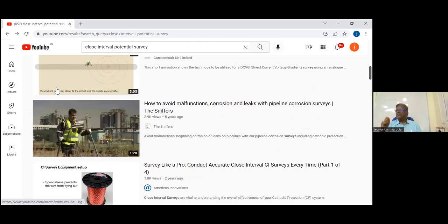Coating is a non-conductive material, so some voltage will return, and we will make it 0, whatever it comes. Then we will go through the line above ground. If the coating is damaged, the pipe will be exposed. The pipe is a conductive material, so there will be a change in voltage. A change in voltage shows that the coating is damaged, so we have to excavate to check the condition of the coating. That is the purpose of close interval.